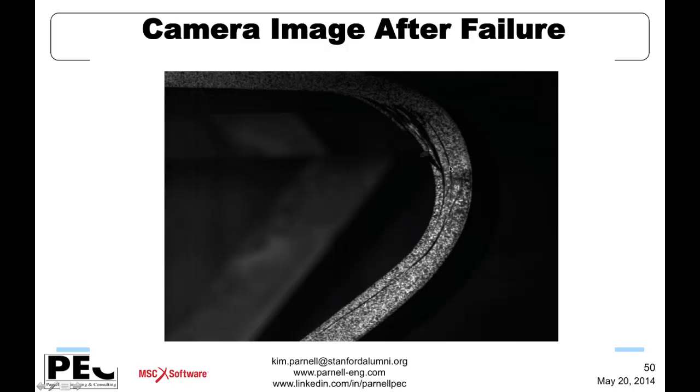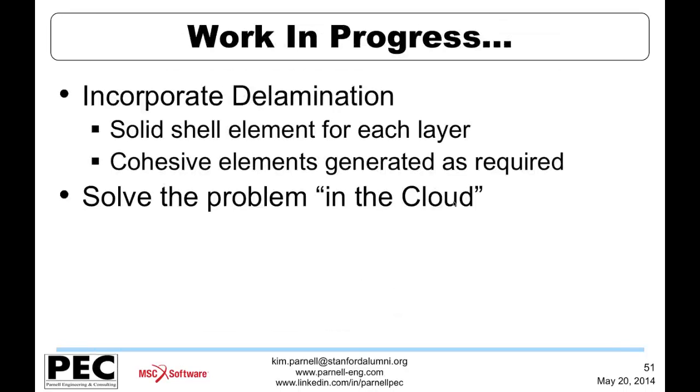You see a number of interlaminar or delamination types of defects that are becoming apparent, and that's also a very important mode of response of this component in particular, and sometimes composites in general, that delamination or interlaminar effects can be really key. So we'll talk about that a little bit here as well.